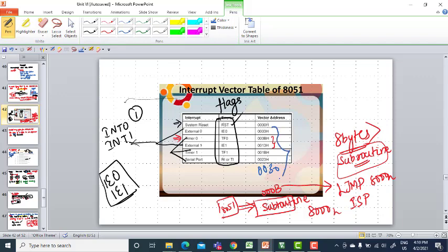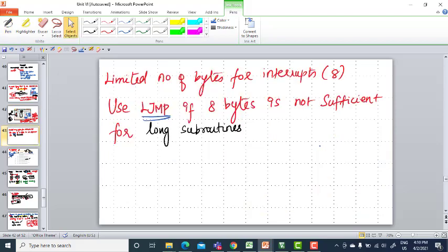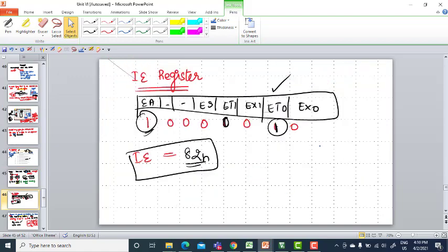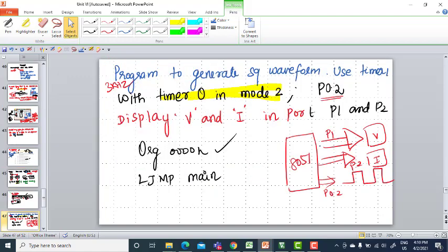This is your interrupt vector table where your interrupt subroutines are saved. If you have any interrupt subroutines, they will be saved here. So skip till 0030H, don't use it for your main program, because those are vector table spaces. It's not an address, it is space.